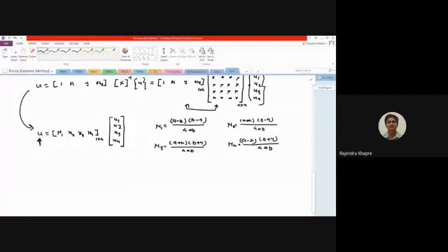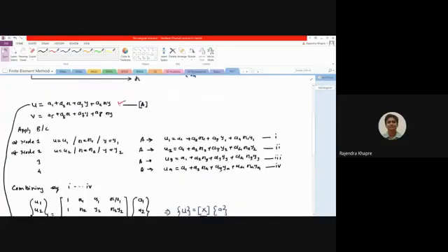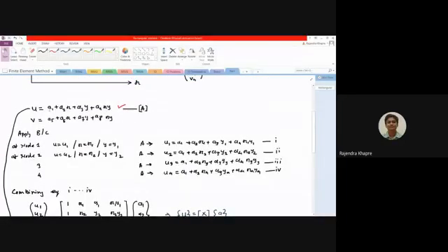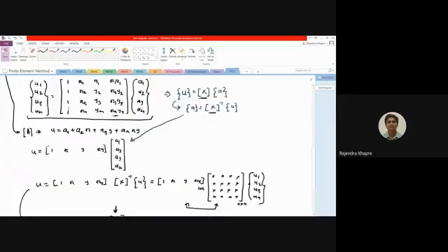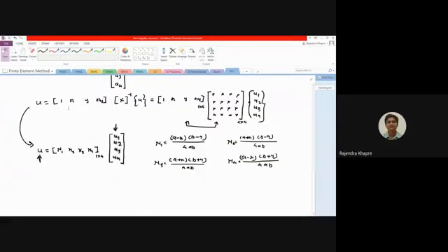This displacement polynomial now depends on the local displacements, or you can say the nodal displacements. So it totally depends on the value of deformation in the x direction at node 1, node 2, node 3 or node 4. So it depends on u1, u2, u3 and u4. When we assumed this, we assumed u equals a1 plus a2x plus a3y plus a4 times x and y. Initially we assumed it depends on the coordinates of the point, but now it depends on your nodal displacements.